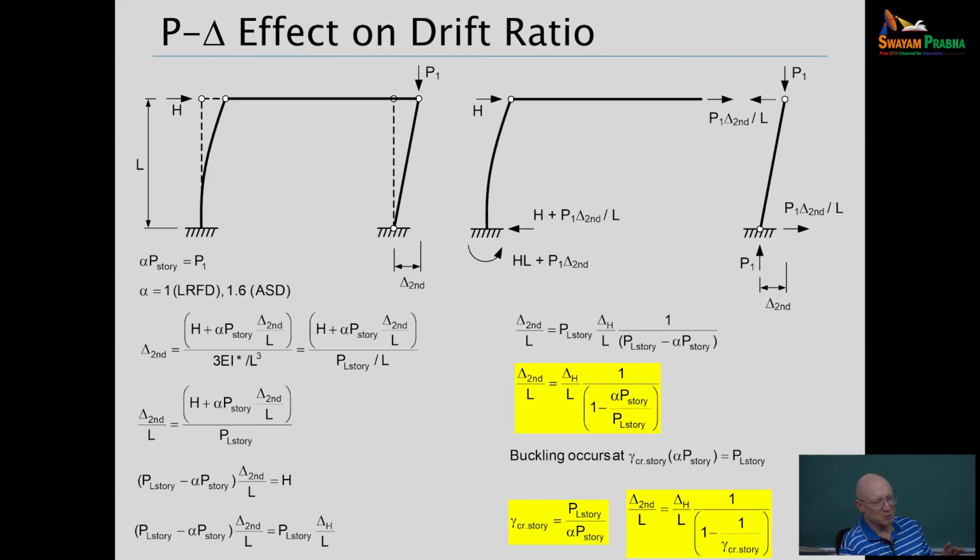So given whatever your structural analysis model is, you can say, okay, I can use my model to get a story stiffness. Do I have some shear deformations that are important in my story? Okay, get your story stiffness, including shear deformations. Whatever it is. Oh, you've got a partial truss system, anything. It's a story sidesway stiffness.